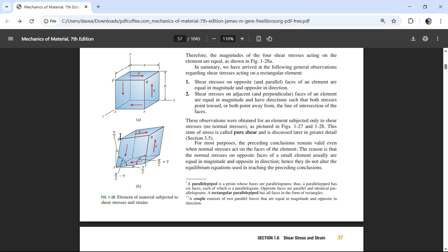Shear stresses cause an object to make a diamond shape, but this doesn't have to be a microscopic chunk of material. It can be a substantial chunk of material. And so what's going to happen is this length is going to increase. If we have this material just chilling out and this length increases, we're going to have an axial stress along this direction, which is along the 45. So along this 45, we're going to have an axial lengthening, tension. And look at this, these two points come together, so we're going to have compression along this axial direction.